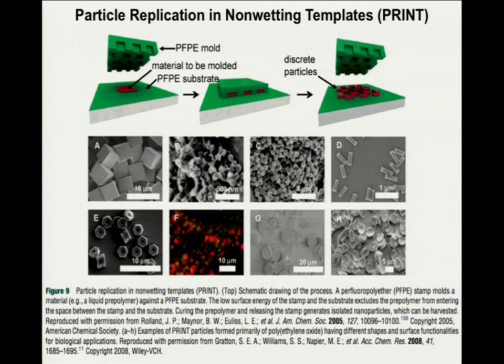There's a seam around the rubber galoshes. That's called the flash layer. So when you mold the plastic from 2 pieces, there's that flash layer that sticks out everywhere. You also get that in microfabrication by stamping. But if you have a sufficiently low surface energy stamp, like perfluoropolyether, which is a Teflon-like material, you can smash it into this prepolymer to get discrete particles.